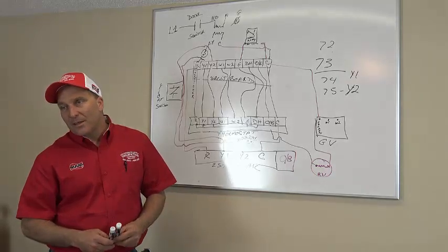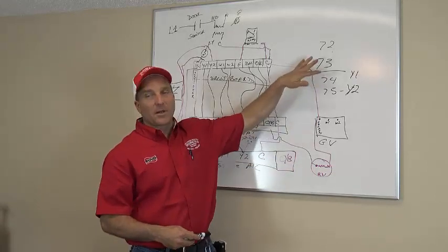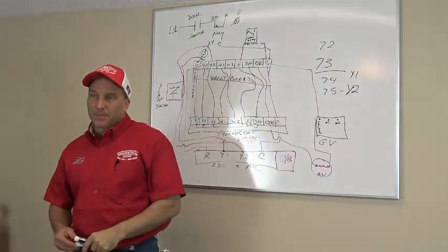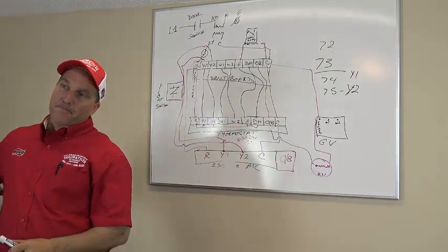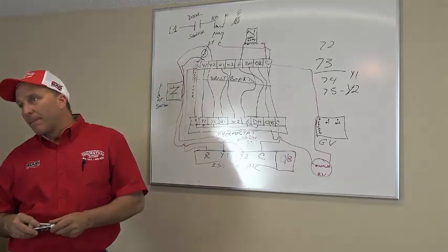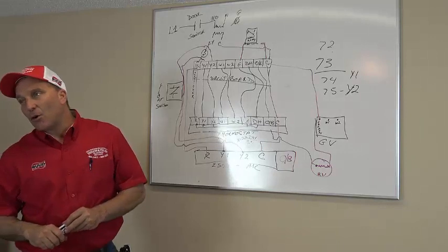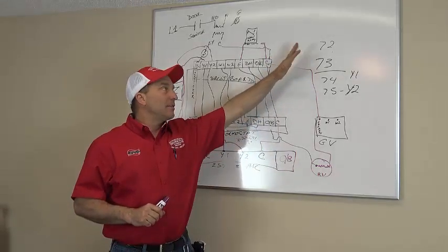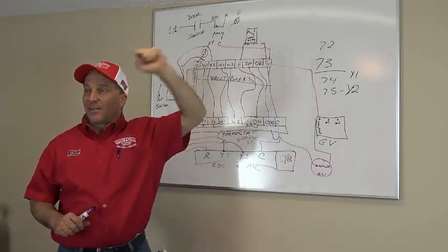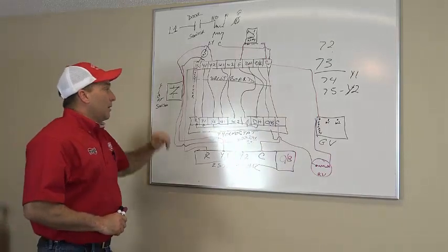Well, I'm going to tell you this. If the humidity level is still higher than what it needs to be, it'll still go up a couple degrees and then dehumidify right on back down 3 degrees below, if that's the way it's set. So if it's set on 73, it'll cool down to 70. And then if it's still calling for dehumidification, it's going to lower that temperature down to 70 now. It's like you got your thermostat set at 70 now, okay, instead of 73. Okay? All right.